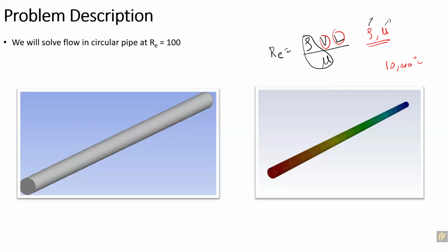And the goal is that the Reynolds number should be matched. If you are running the simulation on your side and I am running the simulation here, the only thing is that the Reynolds number should match, and then the simulations will be similar. Okay. When we have the same Reynolds number, our case results will be similar.